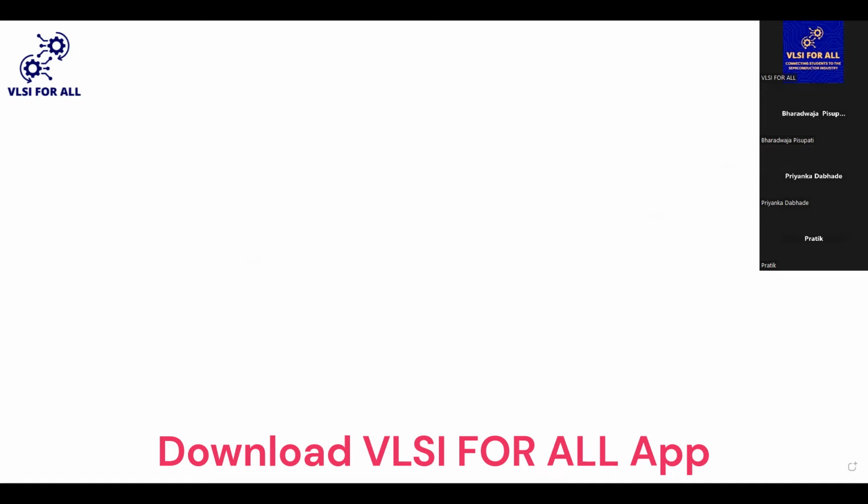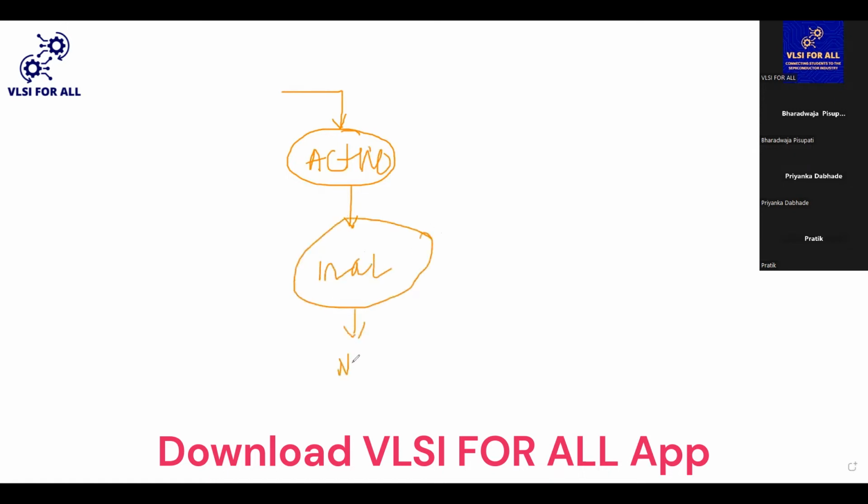So next comes the $display, $strobe, $monitor, and $write. In order to understand these particular things, we need to first understand what the stratified event queue is. As we have discussed earlier, this will be the active region. After the active region, it will be the inactive region. After the inactive region, it will be the non-blocking assignment region. And after the non-blocking assignment region, it will be the monitor region. And after this monitor region, it will go to the next time slot. So it comes from the earlier time slot, and it goes to the next time slot.